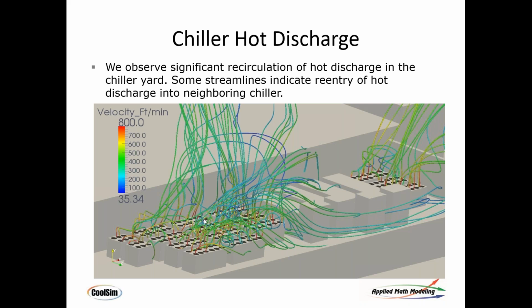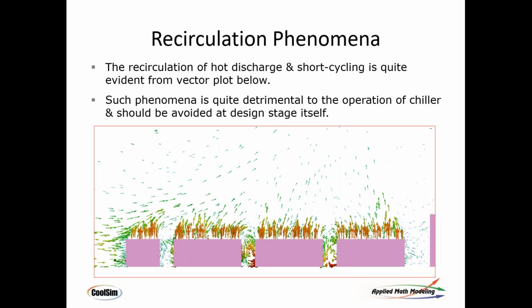And you can see already under a wind condition here that we've got some recirculation going on. It's dropping down, and it's going to be pulled into those inlets. You want it to go straight up in the air and go away. But because we have this blunt body over here called a wall, as that air comes over that wall, it's going to start to create a low pressure area and start to cause issues. Now, this is shown here as well in a vector plot. Same exact situation, we're just looking at it from a side view. And you can see the recirculation coming down and getting sucked into the intakes. So we've got issues already with these things being so close together that the outlet is being sucked into the inlet, and it's being caused by this wind condition.